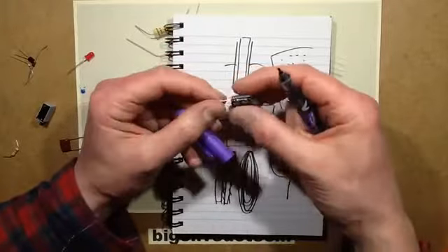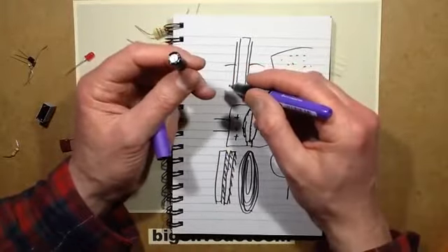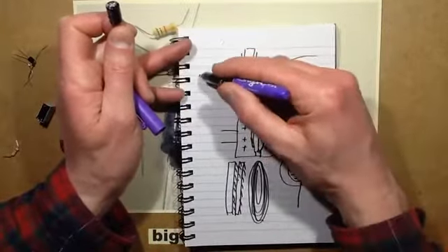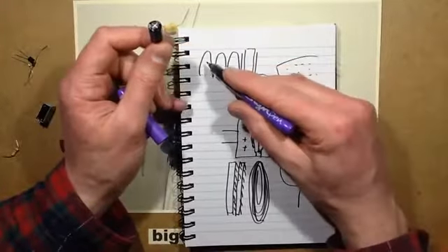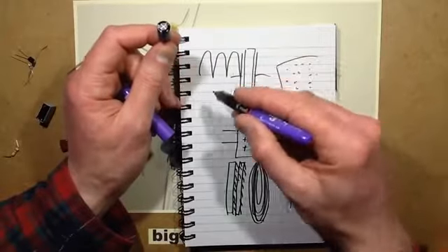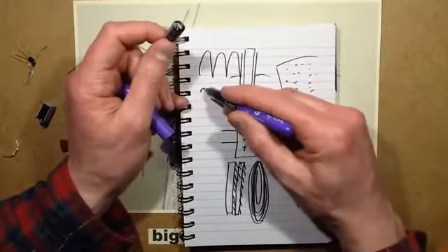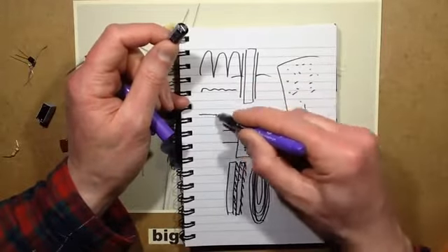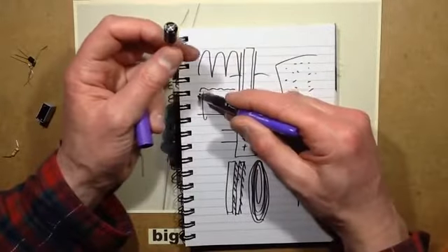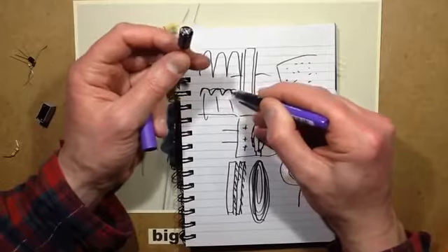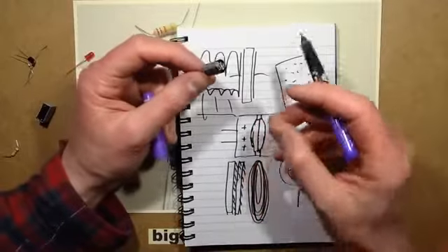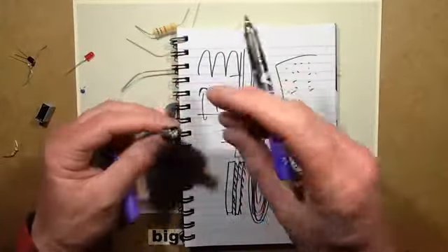When you get large values like this, they're usually used to smooth ripples. Say for instance the output from the mains was rectified, and you had a big peaky full wave rectified AC waveform, which is like the two sides of a sine wave. By putting this across that, it reduces it to a very slight ripple and a nice smooth DC voltage. As that capacitor dries out over time, that ripple will get bigger, and it ultimately starts causing problems when it dips down so low that the electronics can't sustain normal operation. And that's when you have to change capacitors.